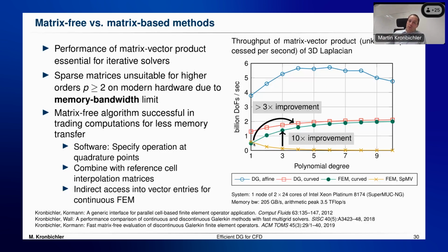If you compare linear finite elements, so linear shape functions, using a matrix, to a high-order matrix-free implementation, then you see that even though you use high order, and everyone was trained to say that high order is more expensive because the coupling is more dense, a matrix-free solver will typically see an improvement in throughput, because the finite element integrals are amortized across the degrees of freedom within an element. And the higher the degree, the more amortization you have within the element. So this is a nice structure. This is a CPU system. You would see very similar numbers on the GPU system.